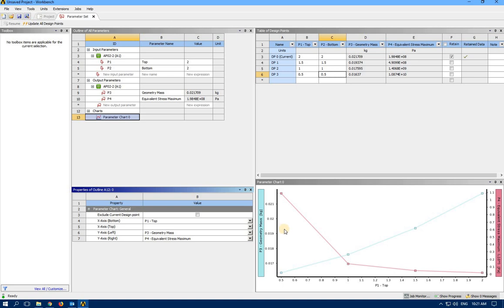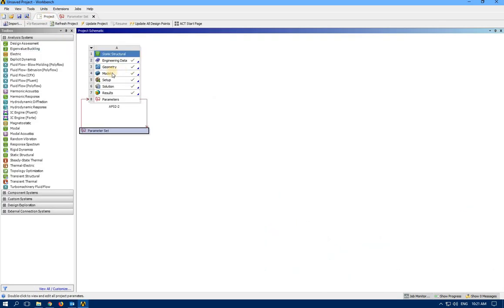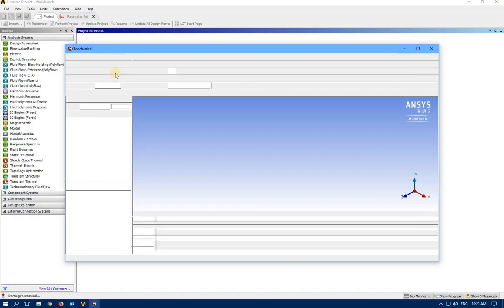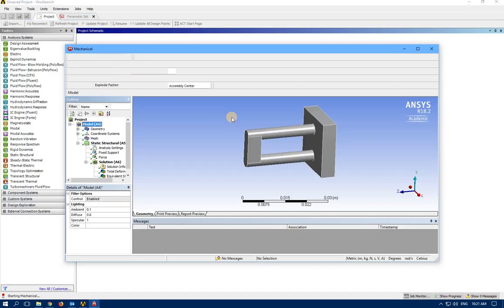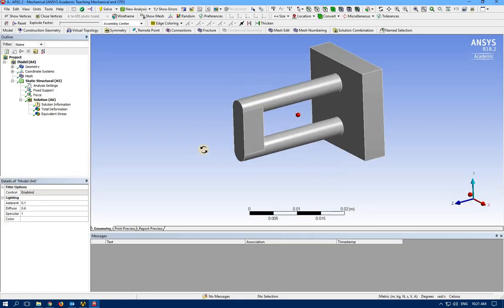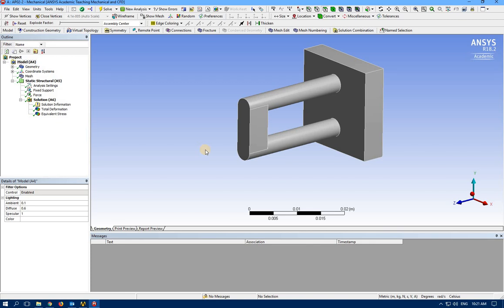different parameters. Let's go back and add one more parameter, like mesh size, because one of the important studies we do is mesh dependency investigation, because your results shouldn't dependent on mesh size, and if you change mesh size, the result difference should be less than, for example, 5%, 3%, 1%. Shouldn't be like a twice or 50% difference.